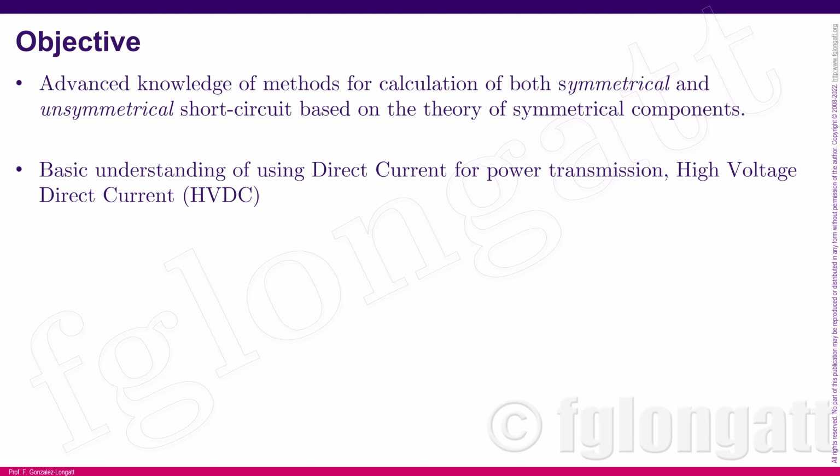Okay, I clarify this and make this point clear because there are many people using bad language. When we talk about faults, those faults can be series or shunt. And short circuit is only a subset of the faults and is basically dedicated to the shunt faults. Then, when we are talking about short circuits, there are different types of short circuits. We are working in a three-phase system, and in this three-phase system, we have different possibilities of short circuit.